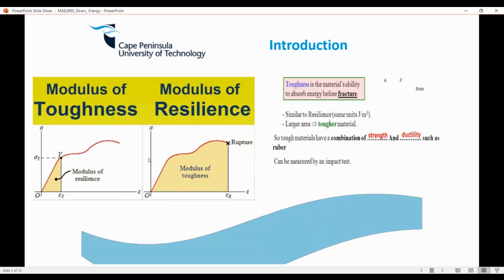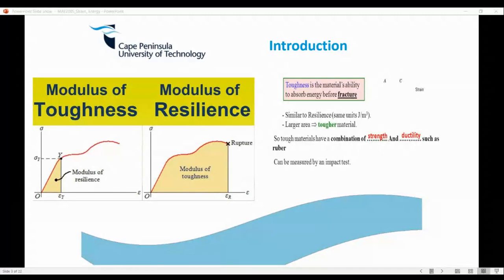Now, there is an application, I was thinking of this yesterday: impact testing. I worked at a company where I was responsible for the materials lab, and I never did any computation. You just take a specimen. I don't know if you've ever heard of an impact test before. It basically has an anvil, it swings, breaks the specimen, and then we record the amount of energy, and it has a specific energy threshold. So I would say that's an application of it, but I haven't used any of the computations within that. But yeah, toughness is the ability to absorb energy without failure under various loads.